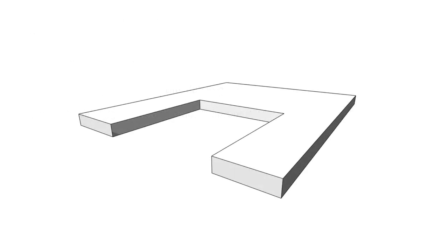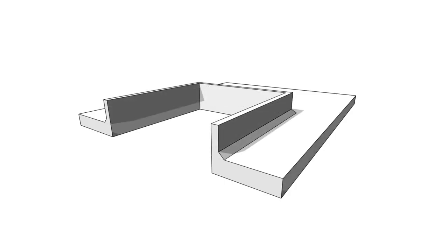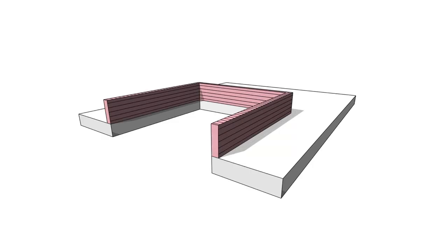An upstand is a generic term for a vertical structure added to a horizontal surface such as a floor or roof. It may be required to provide extra strength around the edge of the object, help with weatherproofing, or even provide a protective barrier to an opening in a floor. They could be formed using the same materials as the horizontal surface, or from a different material entirely.